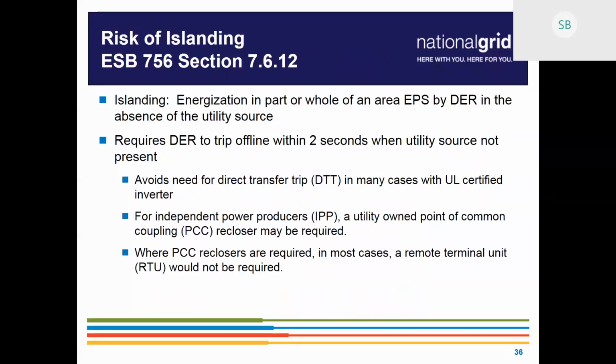And again, this is really specific to inverter-based systems. If you have a rotating machine or something like that, the analysis is a little different because electrically those look different. But for inverter-based ones, if they're UL certified, in many cases we can avoid DTT.